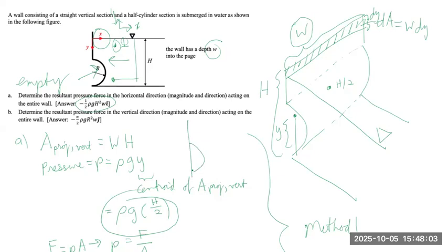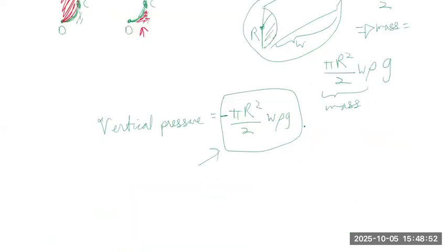And since the semicircular section exists and it displaces this amount of water, there is a vertical force associated with it. So that vertical force must then be equal to the buoyancy force, which is equal to the weight of the water displaced by this semicircular section. And it is basically pointing in the j hat direction, so don't forget that part.